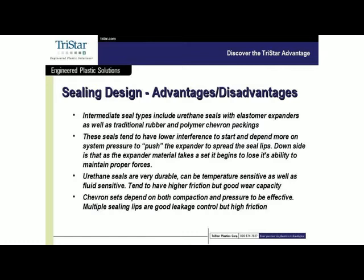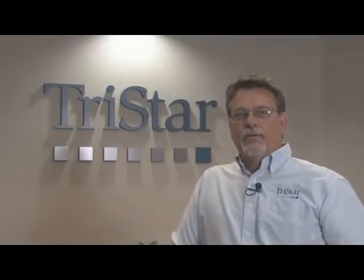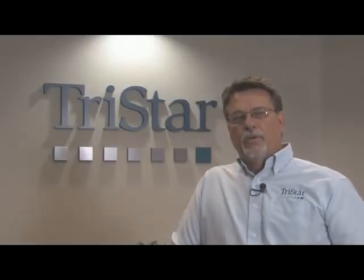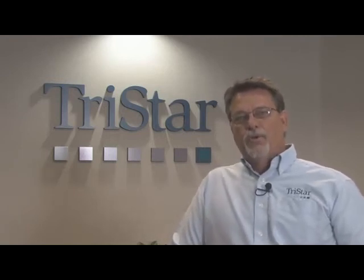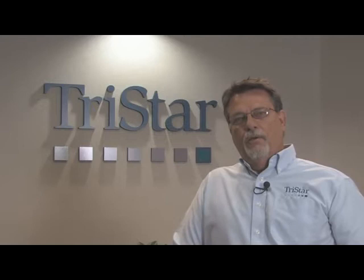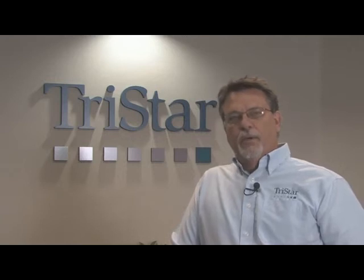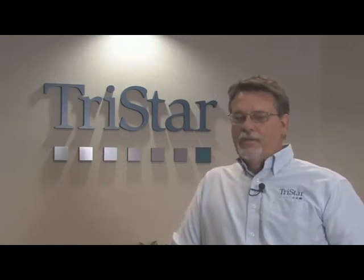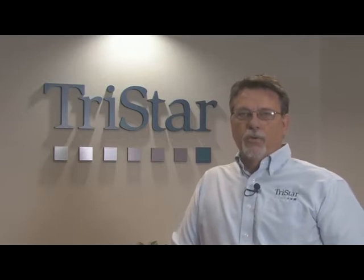The multiple sealing lips is always a good concept in that you're introducing a bit of a labyrinth design. The trick is to be sure that the introduction of all of those seal contact points is not producing too much footprint to where you generate a huge amount of heat. And with that much mass, it's very difficult to get rid of that heat. And as I said before, heat kills both polymers and elastomers very quickly.